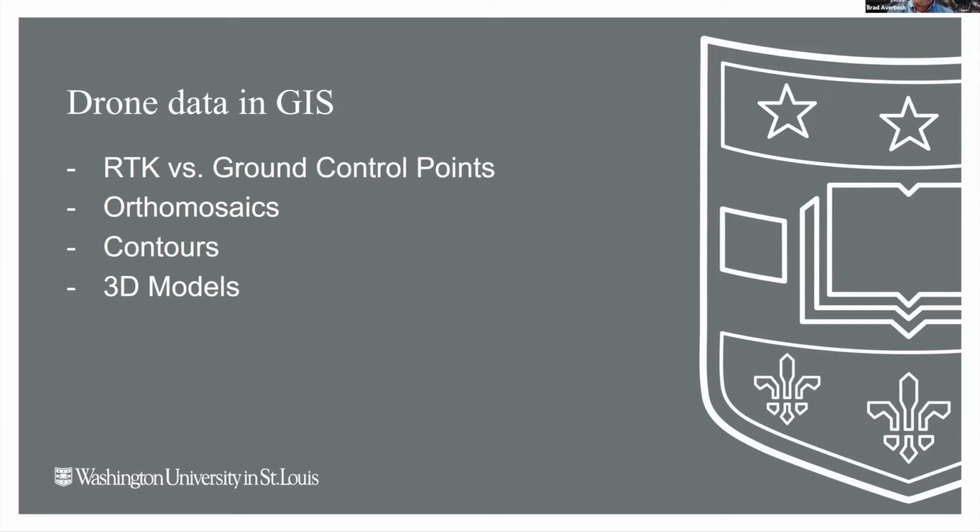So if we just use their vertical datum that they would use to process it, we'd be off by about 30 feet vertically. So when we use our survey data, it now ties it into the vertical datum of Geoid 03 that we used when we did our survey. And so we get really accurate vertical data, which again is probably in the 1 to 2 inch range, which for vertical is pretty good. And it's much more than what we need. If we were within 6 inches, that would probably be fine for what we need.